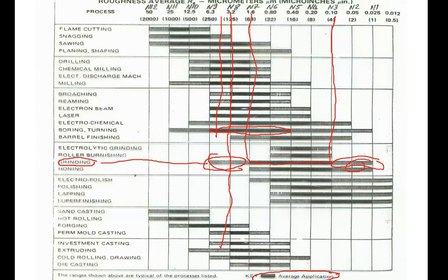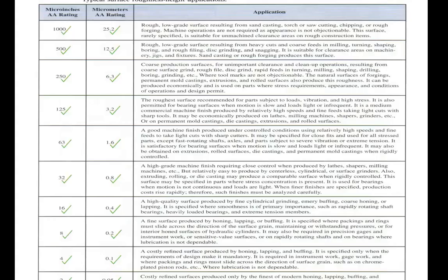We can expect that the roughness value will be maximum 6.3, and minimum, from here the darker part corresponds to this number, 0.4 micrometer. Okay, this bar chart is valuable to see such things, to find the answer of such questions. Which process is recommended under normal conditions to apply for having which roughness value? Well, we refer to this table and then try to answer.